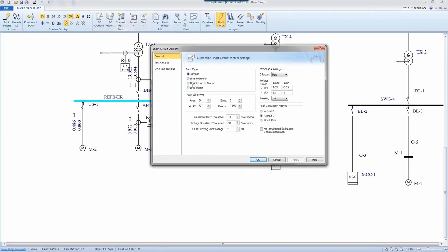This type of fault is not new, you have seen them before in ANSI. This is the very same mechanism that we have in ANSI to define the threshold, over or under which you would highlight the buses. If the voltage value drops below a certain point, or goes above a certain point, we highlight them. This is not a new concept. Of course, the terminology and name of the standard has been replaced here.